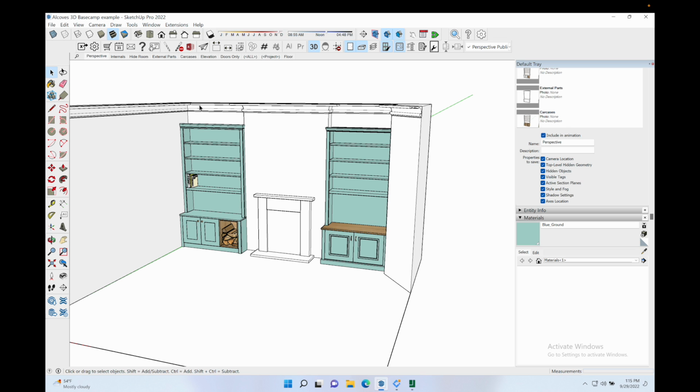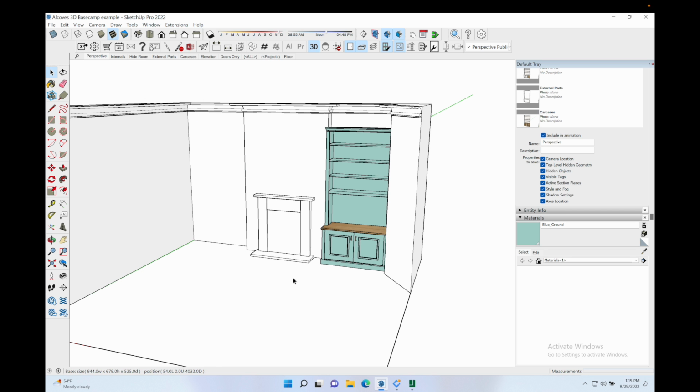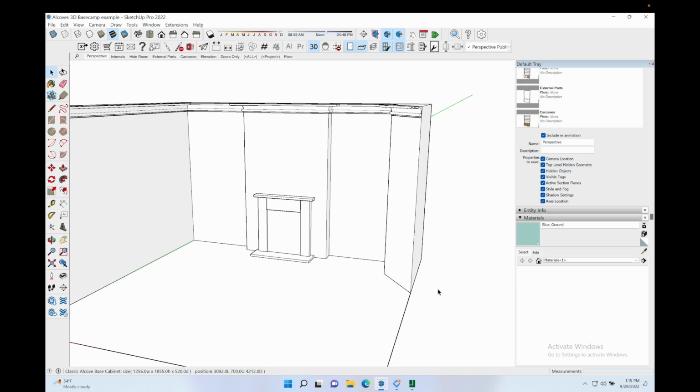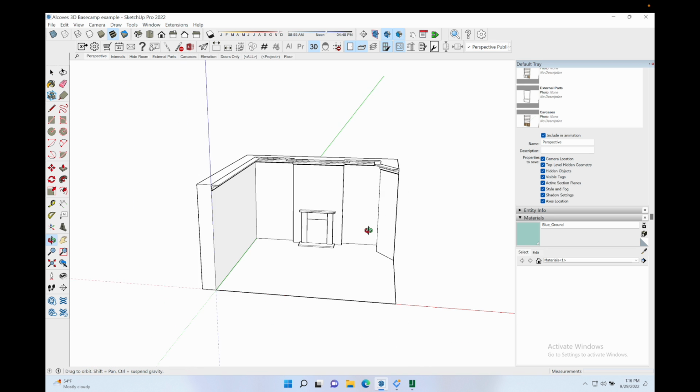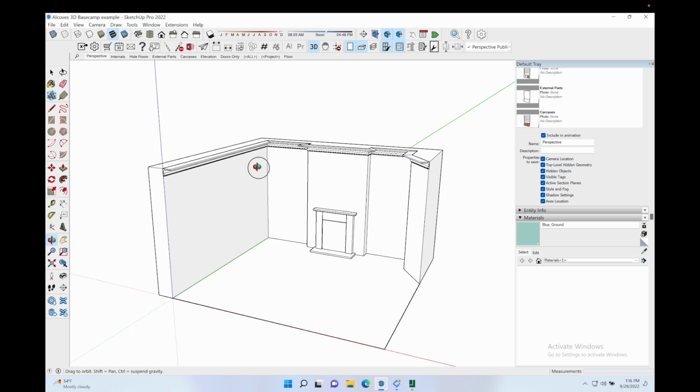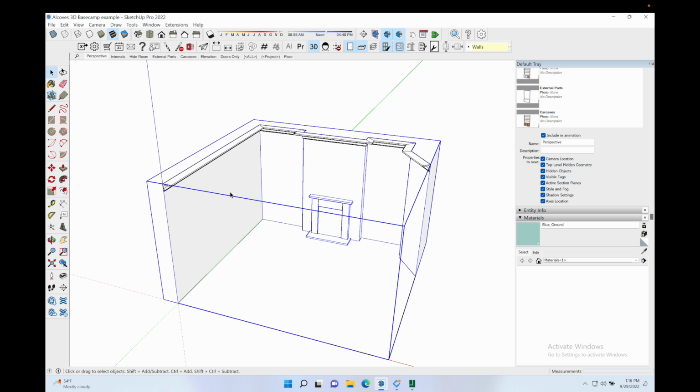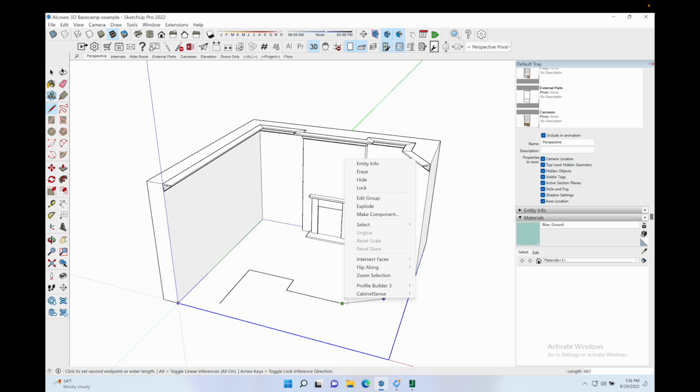Now let's just have a quick look at how a drawing like this is put together, to show you how easy it is, and to show you my particular workflow, which allows me to isolate things by scene. So I'll usually start by drawing my walls. I won't go through that. If you're a SketchUp user, you'll be familiar. You can just click. This is snapping to that axis, the green axis. I can type in a length before re-clicking. So I've just gone ahead and typed. You see it down the bottom right there. Hit enter, and then I can follow. See it snapping to that red axis. I know it's at 90 degrees. Again, type in, hit enter, and I can just carry on drawing in that way.